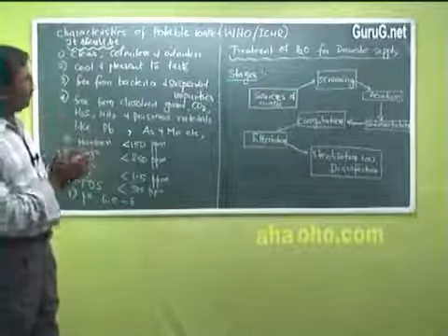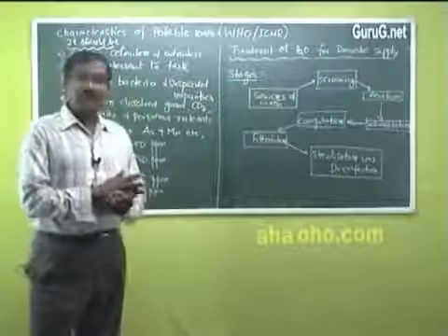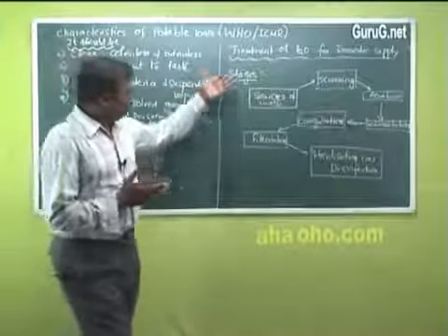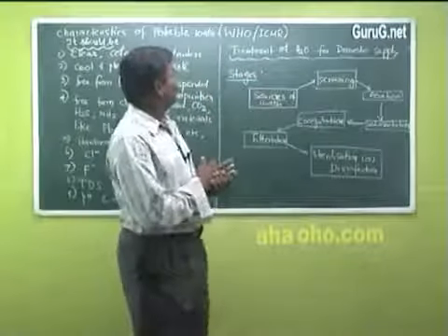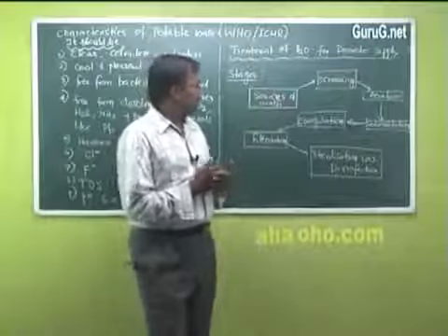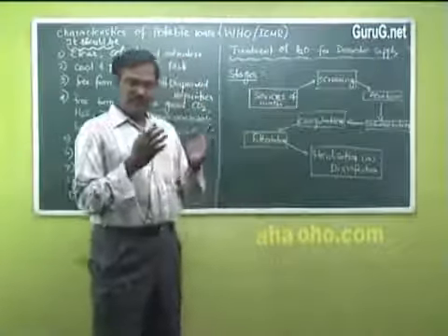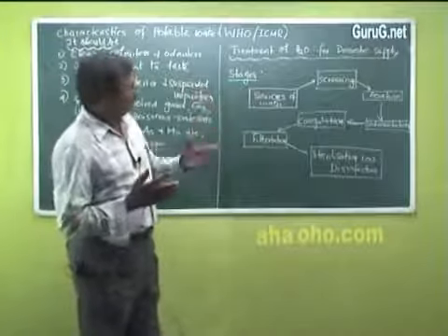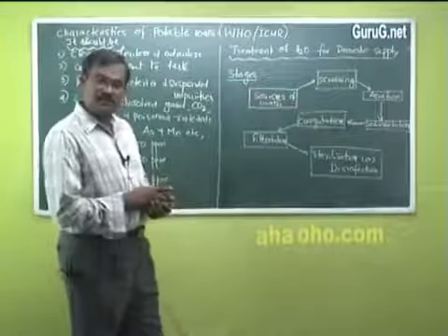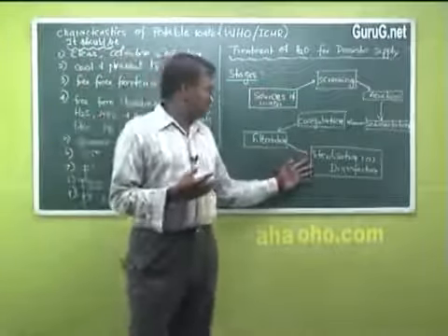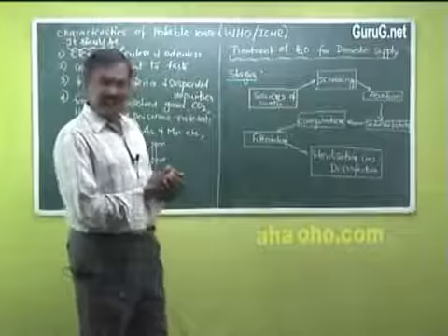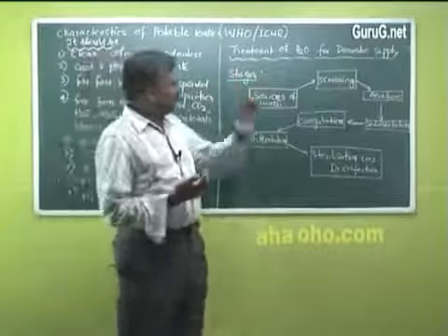And the water which we are getting from various sources does not have all these characteristic properties. So it has to be purified through various stages to get pure water for domestic water supply. So these are the various stages for water to be supplied for domestic purpose. Screening, it is a very, very simple thing. Screening, aeration, sedimentation, coagulation, filtration, and the important process, the last step, sterilization, nothing but disinfection, removing the bacteria and other things.